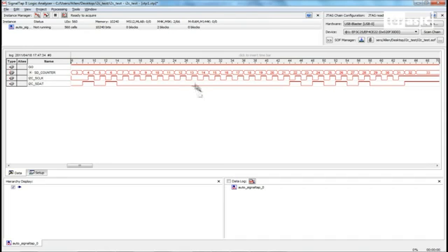Next, we have to specify a register address. So our register address is 0, so it's 00000000. And over here, the acknowledge signal is also low, so the slave acknowledges. And then we write a value of AA into our register, which is 10101010, and the slave acknowledges.